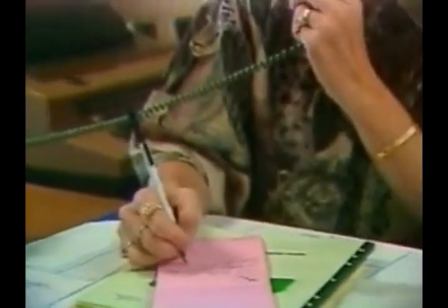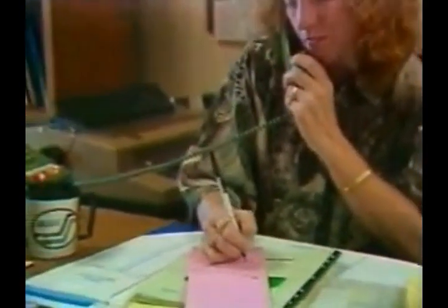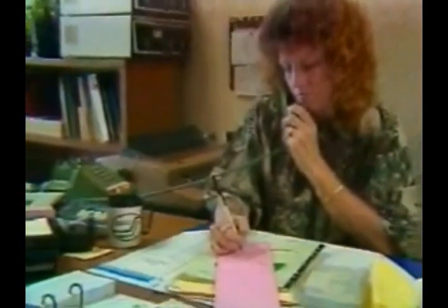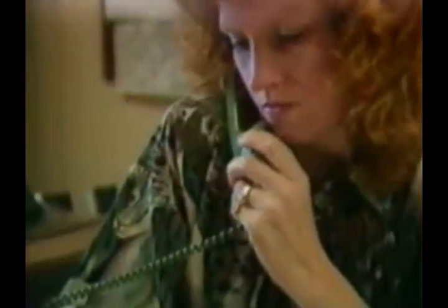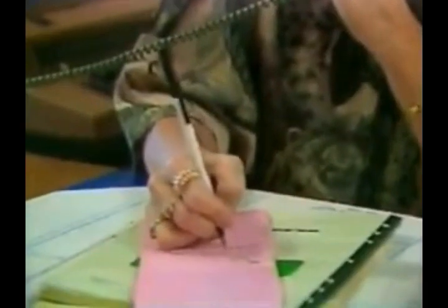Essential information includes hole diameter, total depth to be logged, and peculiarities of downhole conditions, such as the type of drilling mud or a deviated hole. Knowledge of these on-site factors is often critical in determining if special equipment will be needed at the well site. At this time, the oil company representative and the service company will often agree upon the amount of lead time required to notify the service company prior to logging.